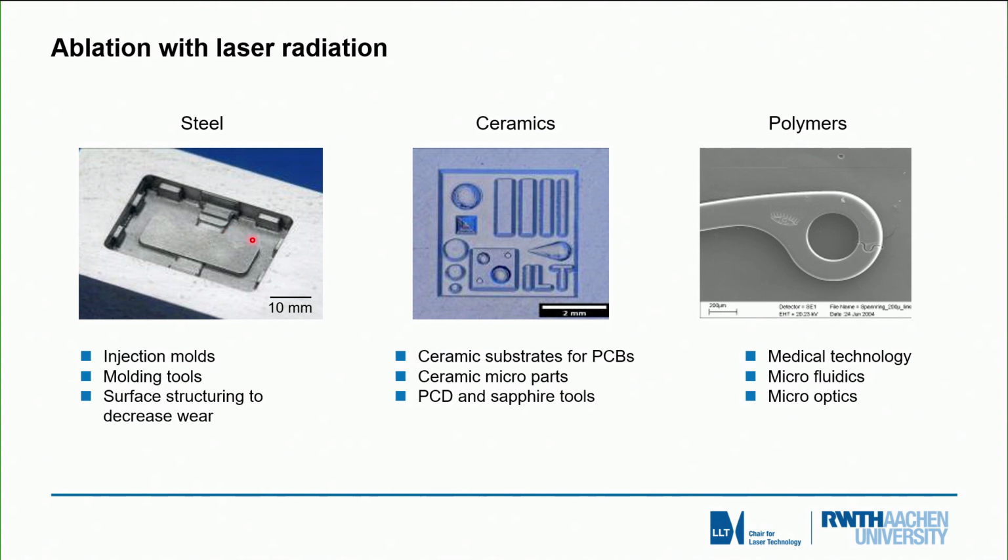and typical values at this point may be interesting to mention. Of pulse rates for such lasers are something like 20 million pulses per second, so this is a very high speed, very low pulse energy. So portion by portion is ablated very precisely, but very fast with very fast repetition rates, high repetition rates, so that we get these macroscopic ablation rates, scaling the laser power, and then get to macroscopic applications in production technology.